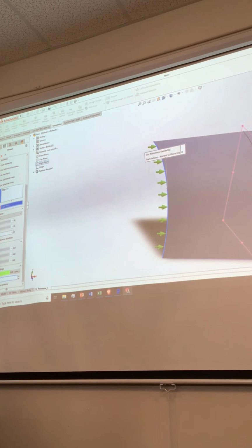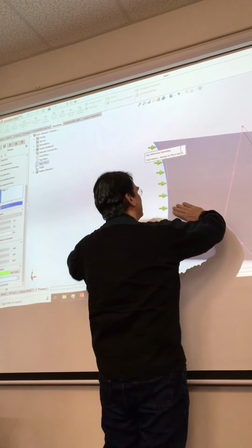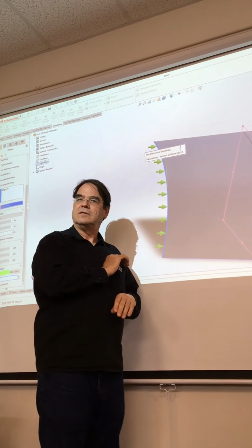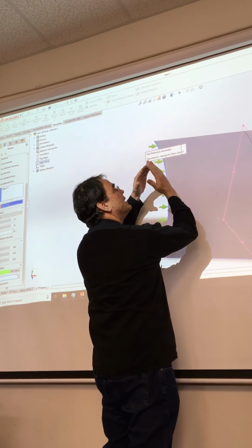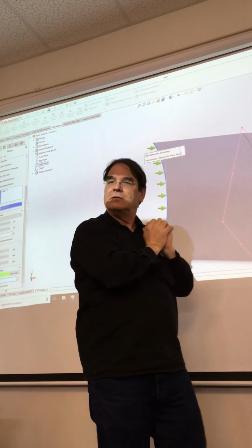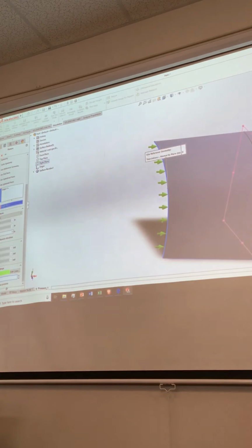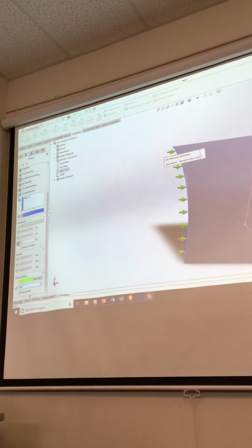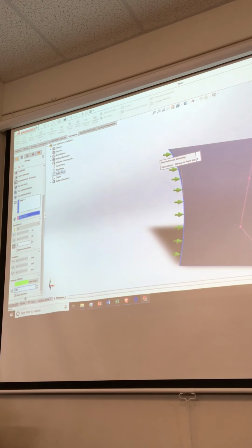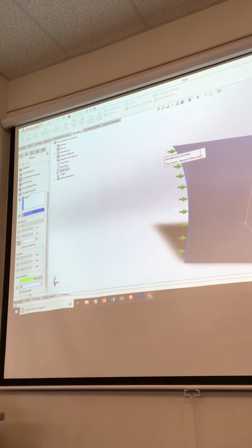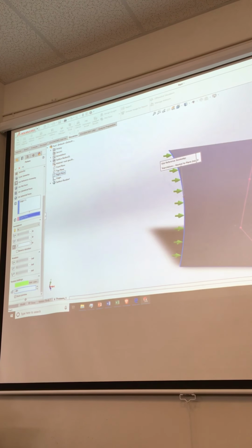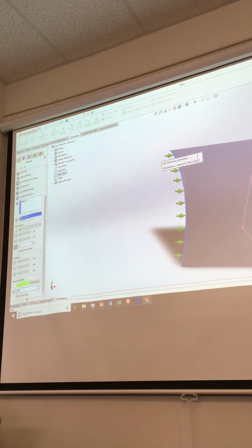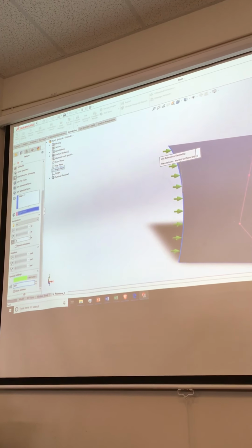There's another part of the symmetrical boundary condition that's in here. But guess what? It's going to be continuous across here. The slopes are going to be continuous across it. It's not going to bend like this when it goes across here, right? It's not going to get discontinuous. They're going to remain smooth, right? Things that are out of plane at those conditions are going to remain out of plane at those boundary conditions. The way rotations work is that those are considered the out of plane boundary conditions.